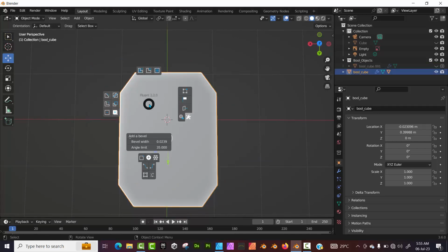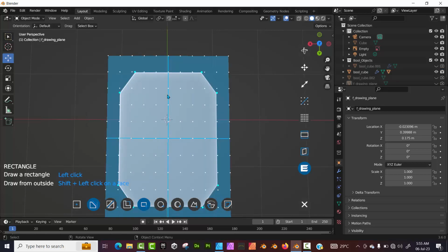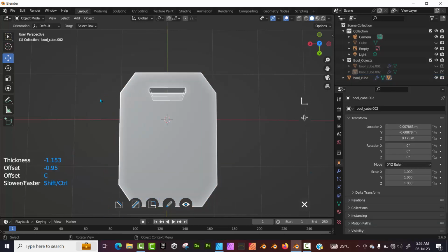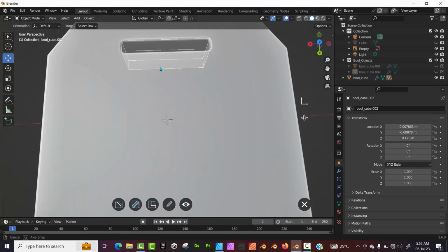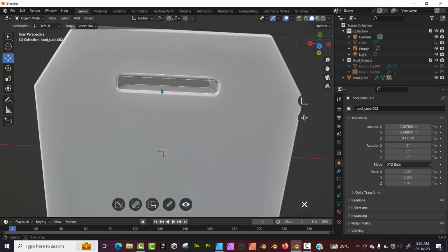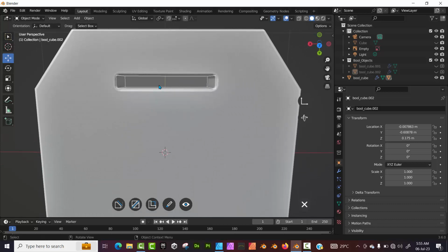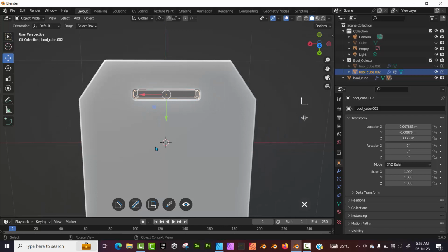So select the object, press F, go over to cut. I think we're going to cut some of those holes, and let's create one right here like so, and just drag this. We can press V to have a clean cut around here, and let's zoom in. So what I want to do is make these edges a little bit smooth. So let's right click and go to first bevel and drag this just a little bit, and that's okay. Let's validate.